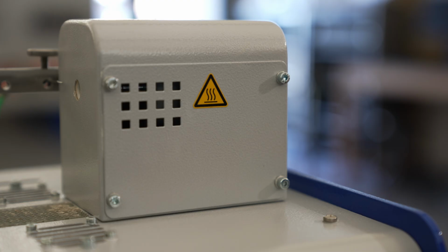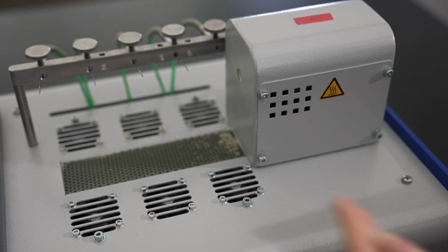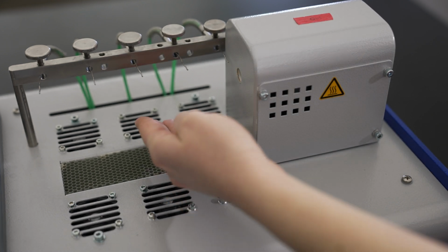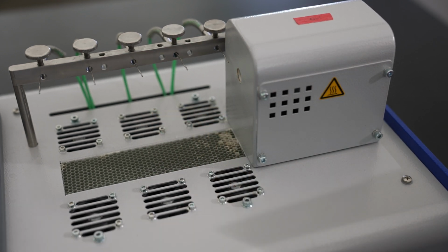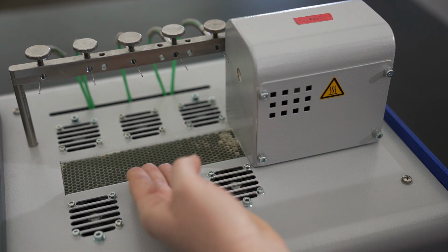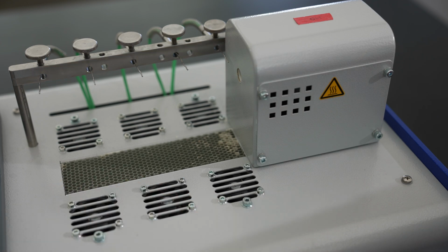The heater housing contains the heaters and a port for inserting the metal sample, rod, or fin. The fans. 3 fans on either side of the sample allow airflow to be blown over the sample, generating forced convection heat transfer. Honeycomb structure. Located at the fan's outlets, this structure helps create a uniform flow before flowing over the sample.